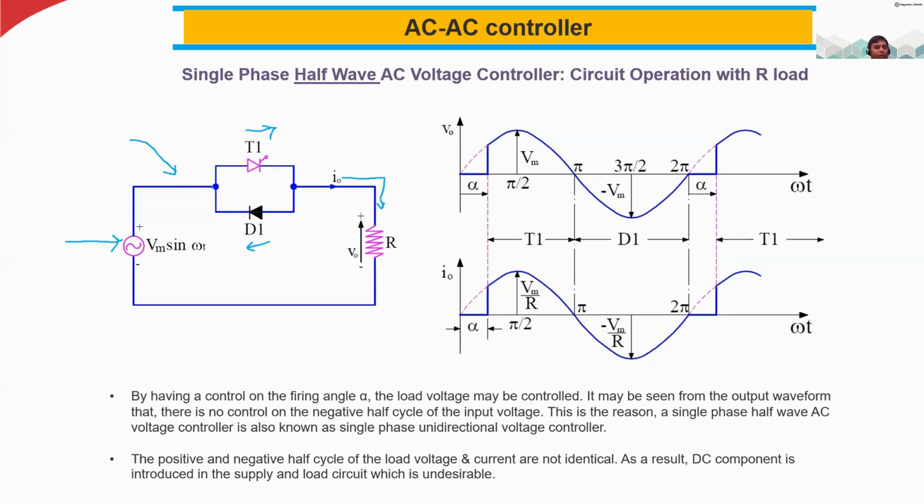So now we will study this circuit. You already know how this SCR works. Whenever you apply the gate voltage and also give the forward bias, meaning plus to anode and minus to cathode, and you apply the trigger signal or the firing angle to the gate, then this SCR will go to the forward conduction mode.